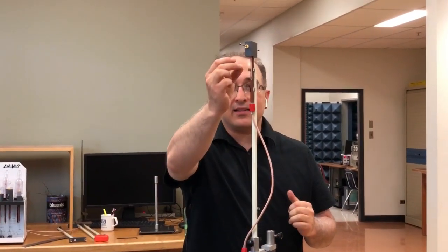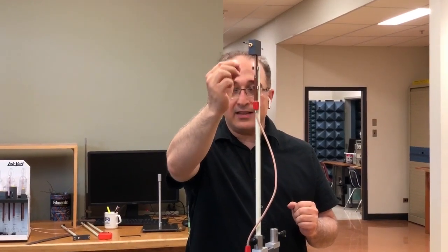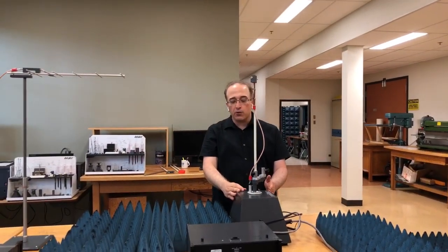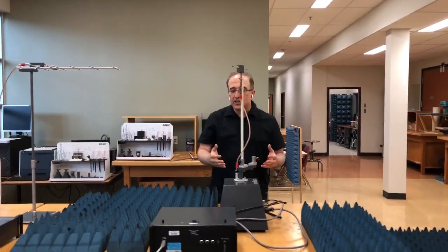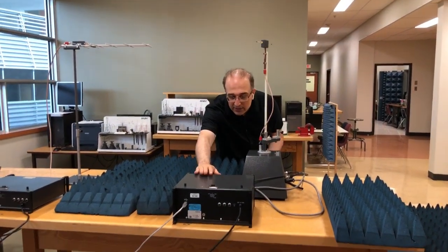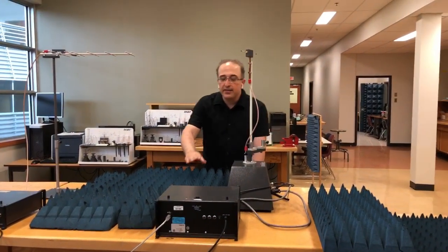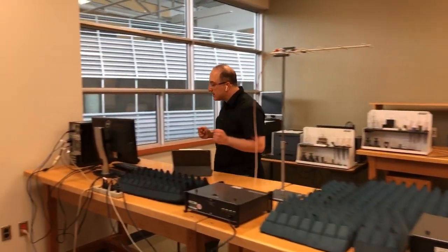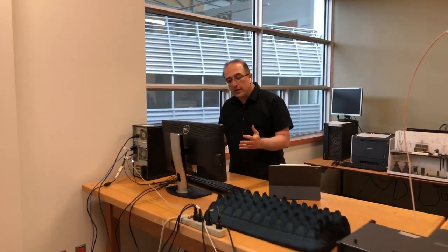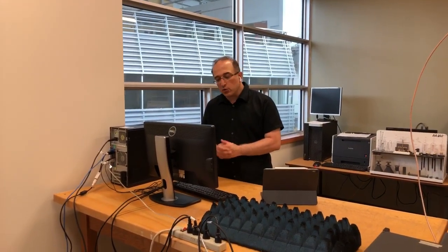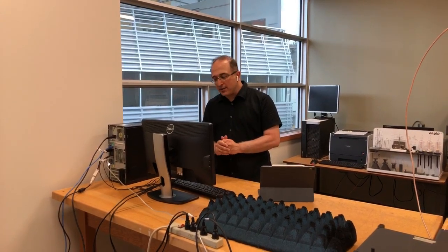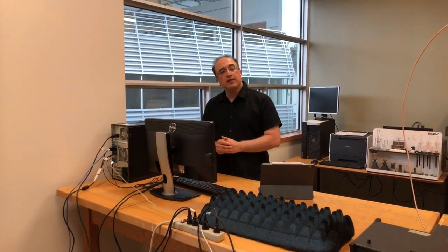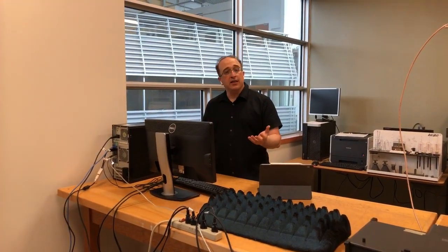So this receiving antenna is going to receive the electromagnetic radiation coming from the Yagi-Uda antenna, and this system is going to convert it to voltage for us. Then this received signal will be communicated to the data acquisition interface that we have here. This data acquisition interface is connected to the last component of this training system, which is the computer in which we have the software. The software is going to plot the radiation pattern for us, and it has some processing capabilities, for example, calculating the half-power beamwidth of the antenna.